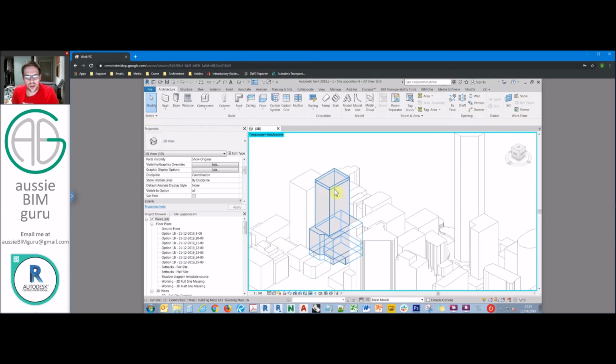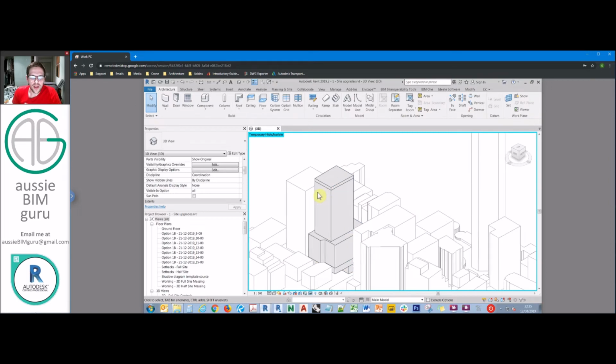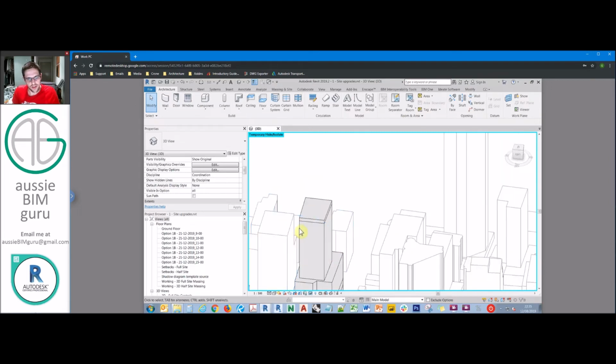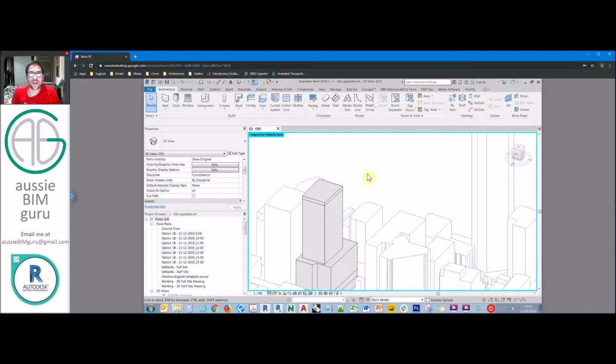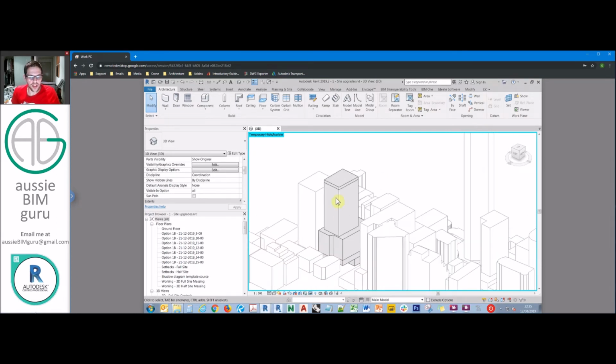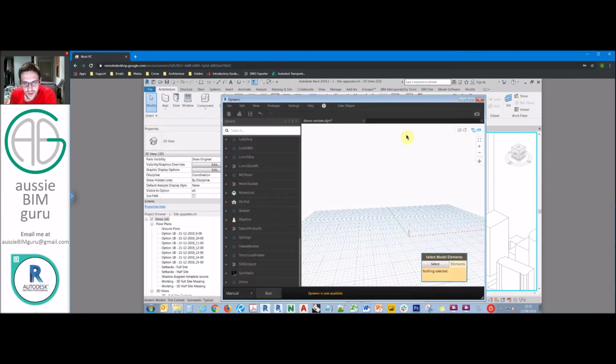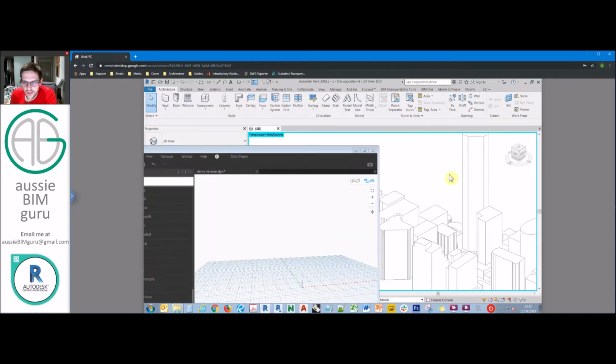You recall that we offset our sensors slightly outside our building. That's so that if you have a sensor on the back side of the building, when it checks a view, it clashes with the building, so you can deal with self-intersecting views. Otherwise, it would just go straight through the building and would think that it can see the building, which is incorrect. So now that we've got these, we can just go back to Dynamo, move this off to the side,